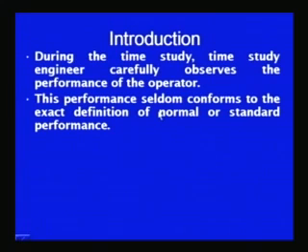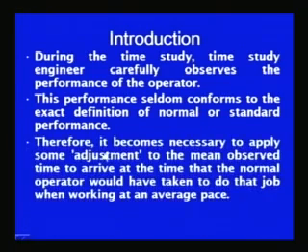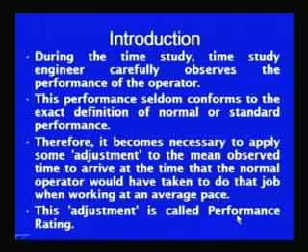The performance of the actual operator seldom conforms to the normal or standard performance, and therefore it becomes necessary for the time study man to apply some adjustment factor, so as to find out the average time which a normal operator will take to do the same job, and this adjustment factor is termed as performance rating.